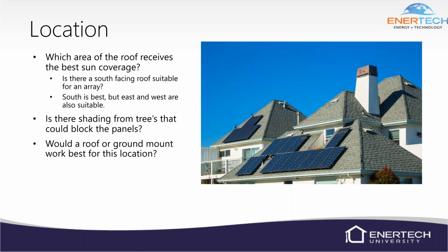By looking at this picture, let's say this is the front of the house. You may want to ask the homeowner, is it okay if we put them on the front of the house? They may not want to see those panels on the front of their home. But if the back of their home is facing north, we obviously can't put them there. So either we're going to have to go with the ground mount or put them on the east- and west-facing roof lines. But definitely ask them that question. Is it going to be a problem if you put them on the roof? They may say, I don't really like the look of it. So definitely take that into consideration.